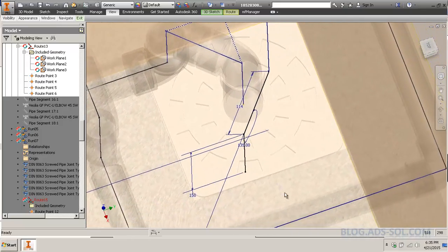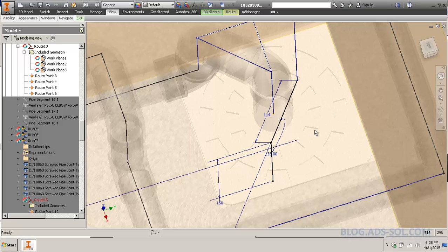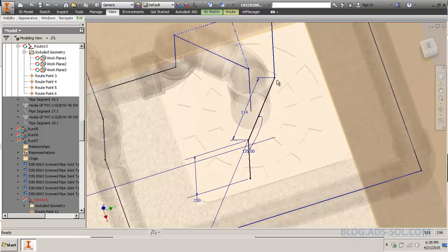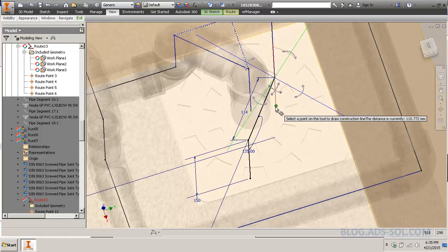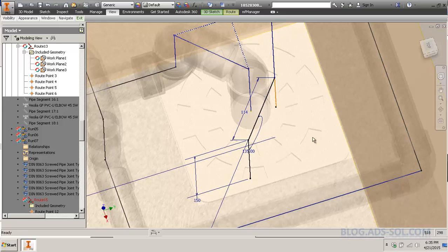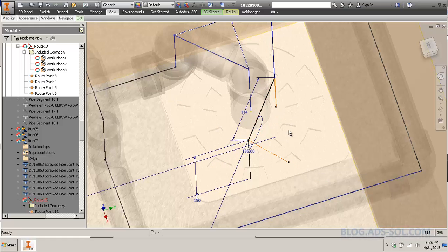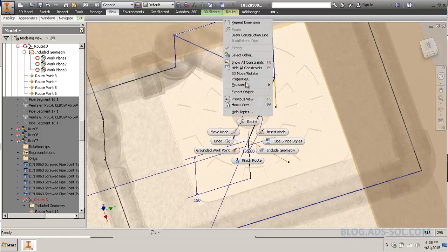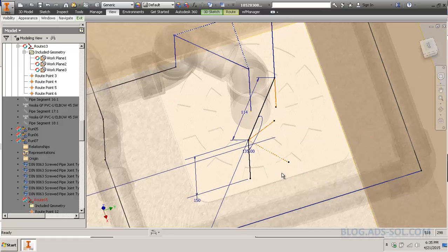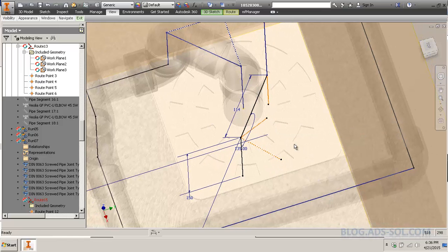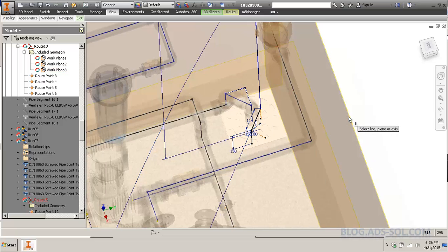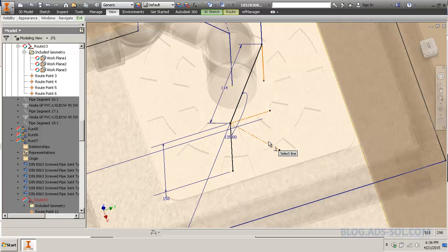Alright, so here's one way to do it. Let's draw construction lines. Just go down, doesn't matter where. We're gonna constrain the projection actually. So from here, construction line somewhere around there. I don't even care that it's skewed. I can start another construction line somewhere in there. You need to constrain the base to make it in plane. So let me try and constrain this to the side wall.